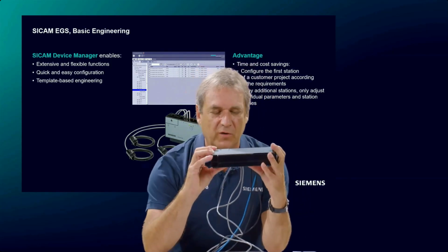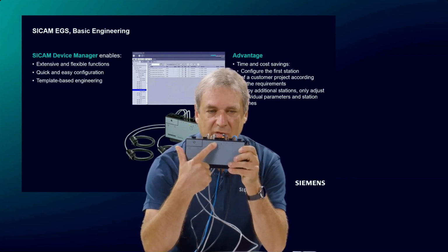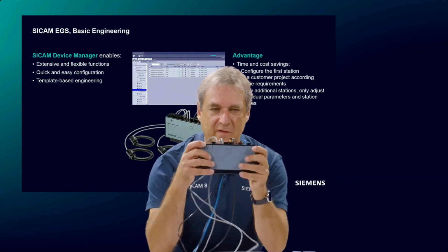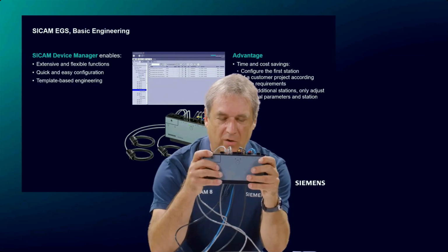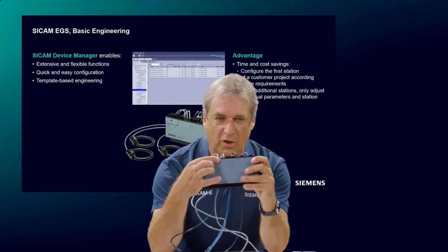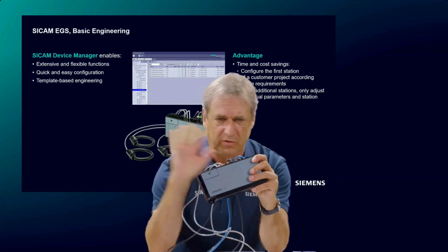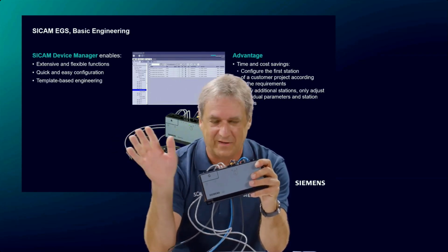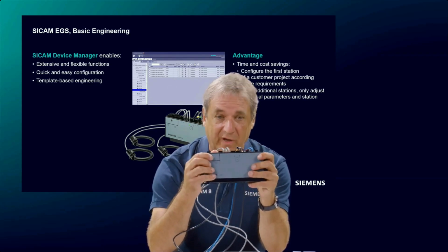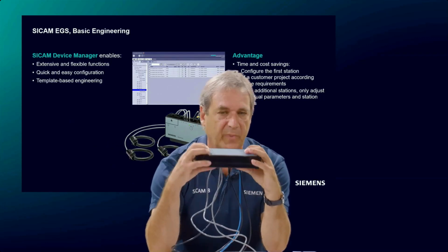Maybe I should also come to the details. Maybe some of you have noticed that there are 2 LEDs, here and here. One of them is the ready LED. As long as the microprocessor inside is running, the ready LED is on. Then you also have an error LED. Normally, you never should see it. It could appear especially if a communication to a SCADA system or to a fuse is broken.